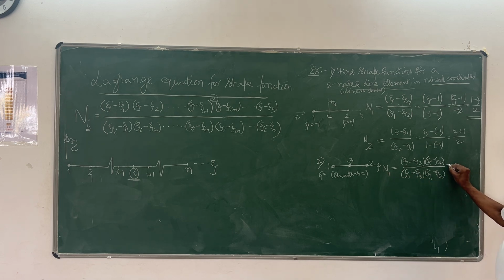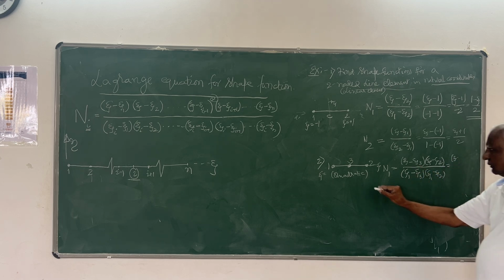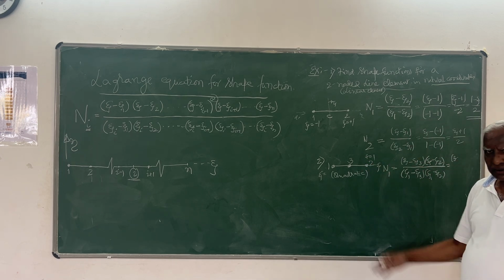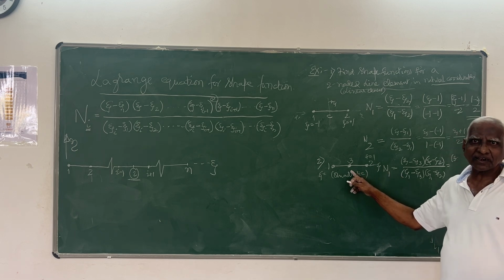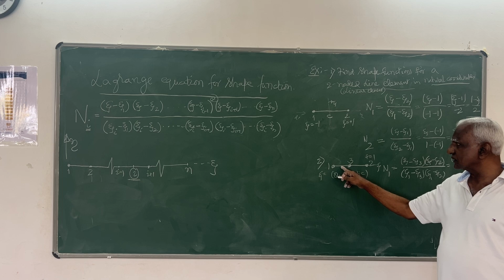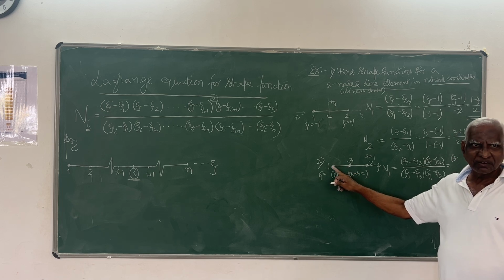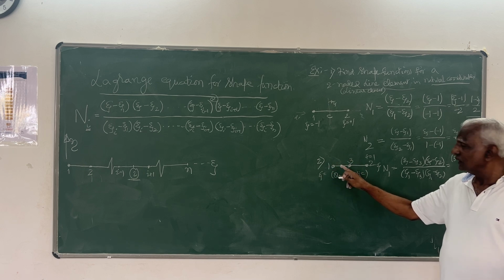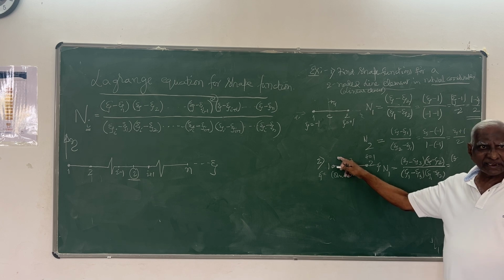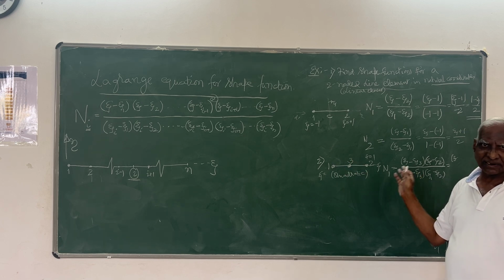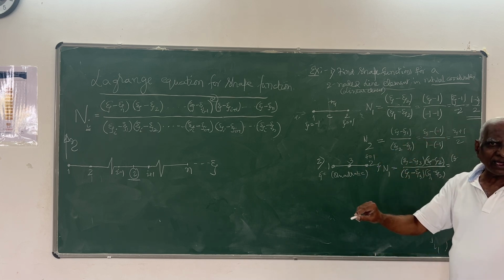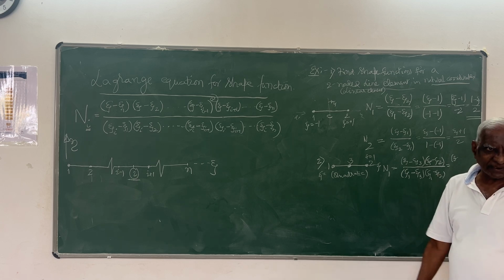Write the coordinates. Here psi equals plus 1 in the natural coordinate. This is the center point, center node. If this node is given 1/3 of the distance from the left, psi equals minus 1/3. If it is at the 1/4 point, psi equals minus 1/4. Like that, wherever that internal node is. So here quadratic means exactly one more middle node will be in the center.